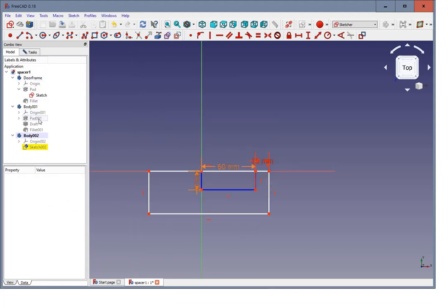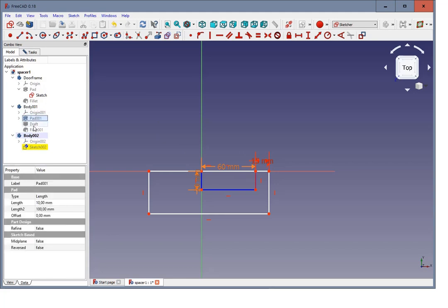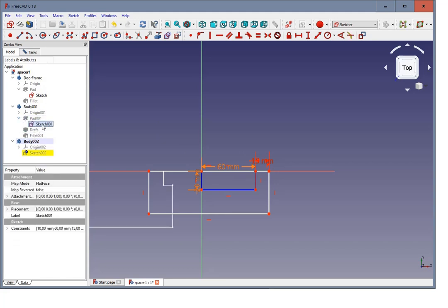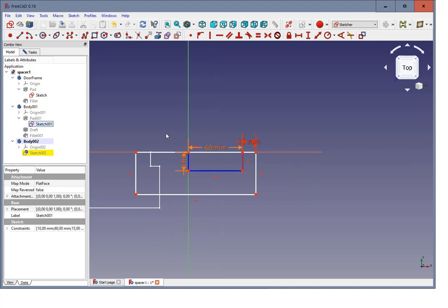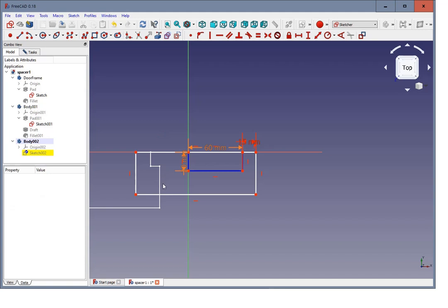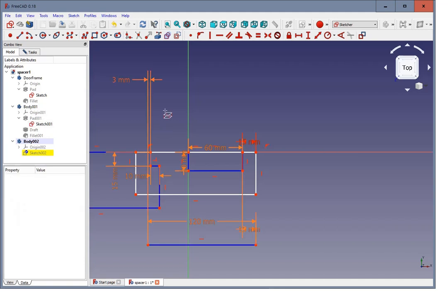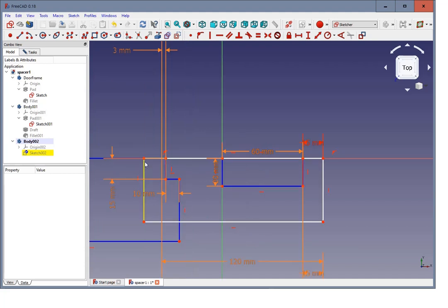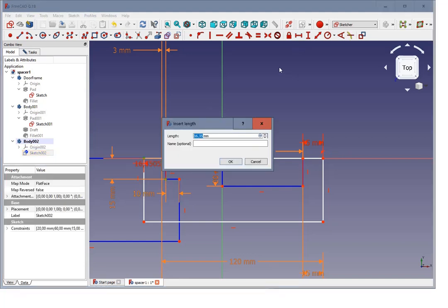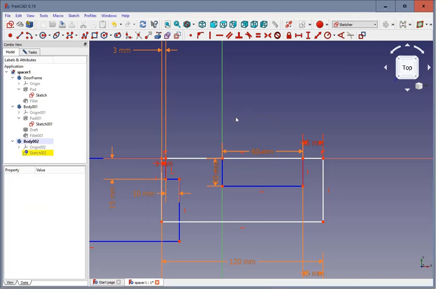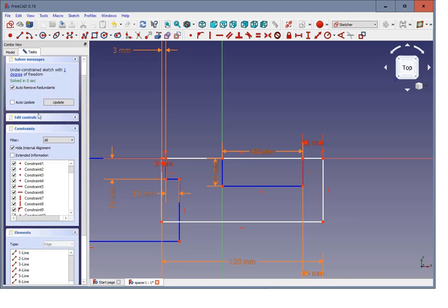So the next is we switch on our sketch from this part, and now you can see why I created it in the same plane, because now it's easier to copy the same here into my construction, and also define that from here to here I want to have an overlap of 3 millimeters, and let's say that is it.